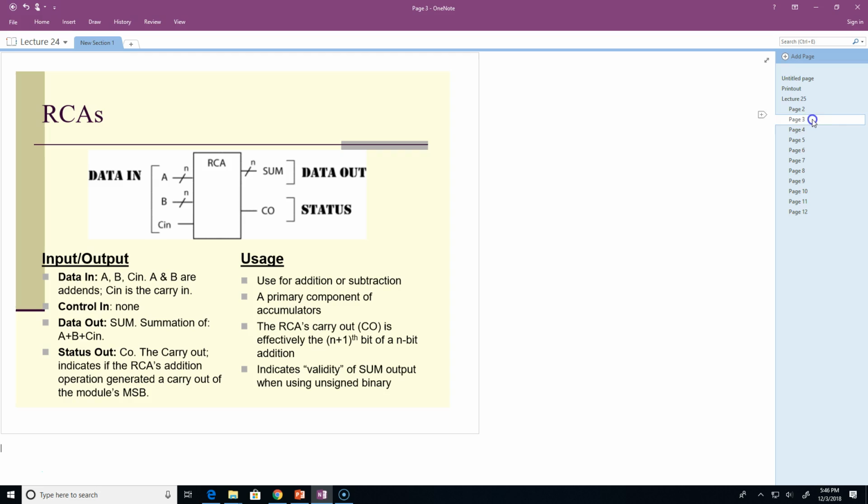Okay, onwards. So what I want to do is go through these foundation modules real quickly, just a quick overview on these things. In general, a digital circuit is a bunch of these modules together transferring information around under the control of something. And what we've been primarily doing is controlling the transfer of information with state machines. Okay, so the state machine, generally speaking, is going to read the status of the circuit and output control signals. So these foundation modules, some of them have control inputs and status outputs. Some of them have data inputs and data outputs.